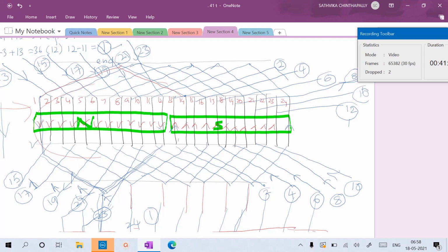In each conductor, mark the current direction, whether upward or downward, based on your assumptions. Draw the ring diagram as per the winding table.